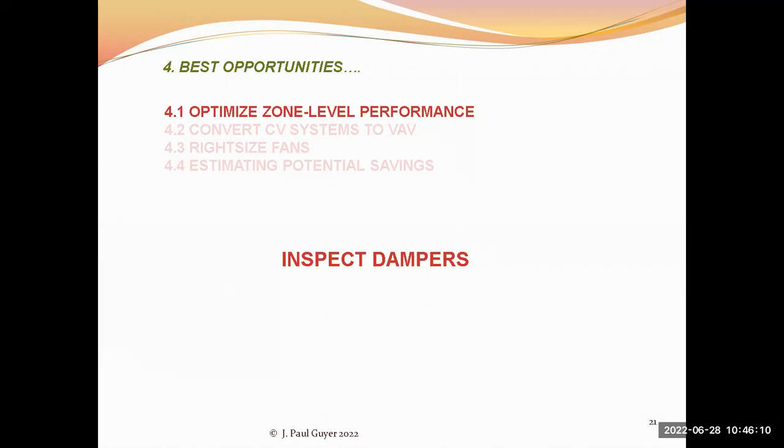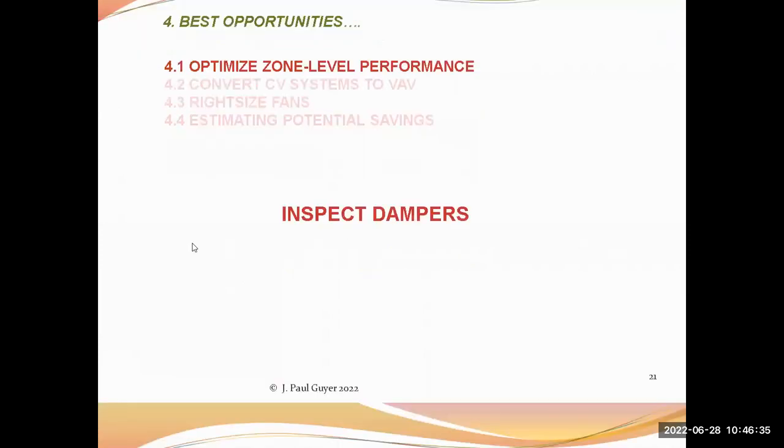Also, if you're using a dual duct system where you've got a mixing box just before the air discharges to the occupied space, that mixing box has dampers in it that need to be inspected to assure that they are functioning properly.